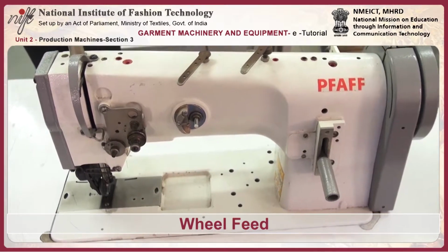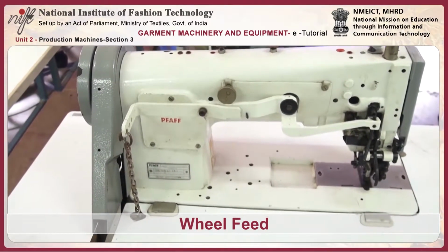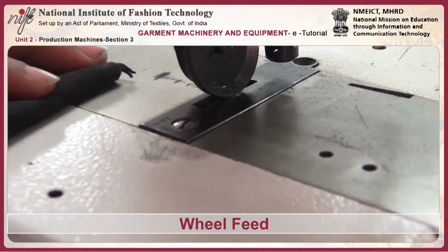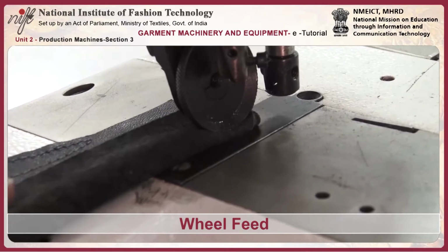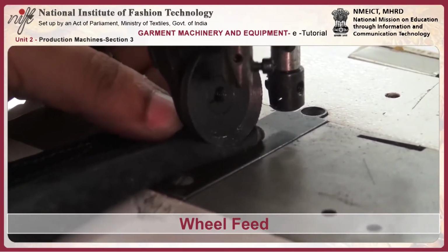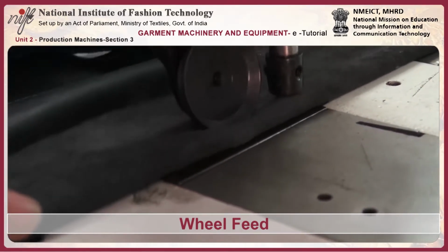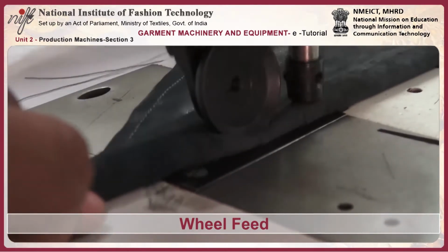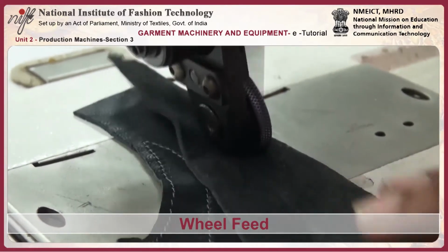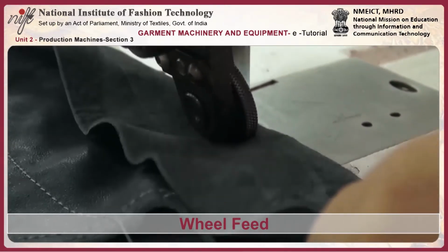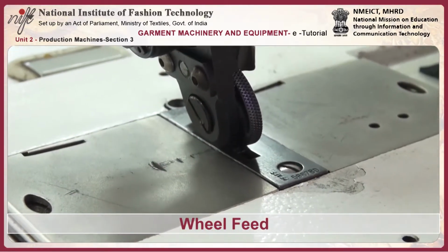Wheel feed. This feed design replaces the feed dog and pressure foot with 2 wheels that contact and move the material. Description: rotating cylinders, either upper, lower or both, drive the feed. These are usually in constant contact with the material during sewing. Applications: wheel feed systems are found extensively in the boot and shoe industries, where they are used for joining and top stitching operations. They are also used in the clothing industry for sleeve setting in ladies and gents outerwear.